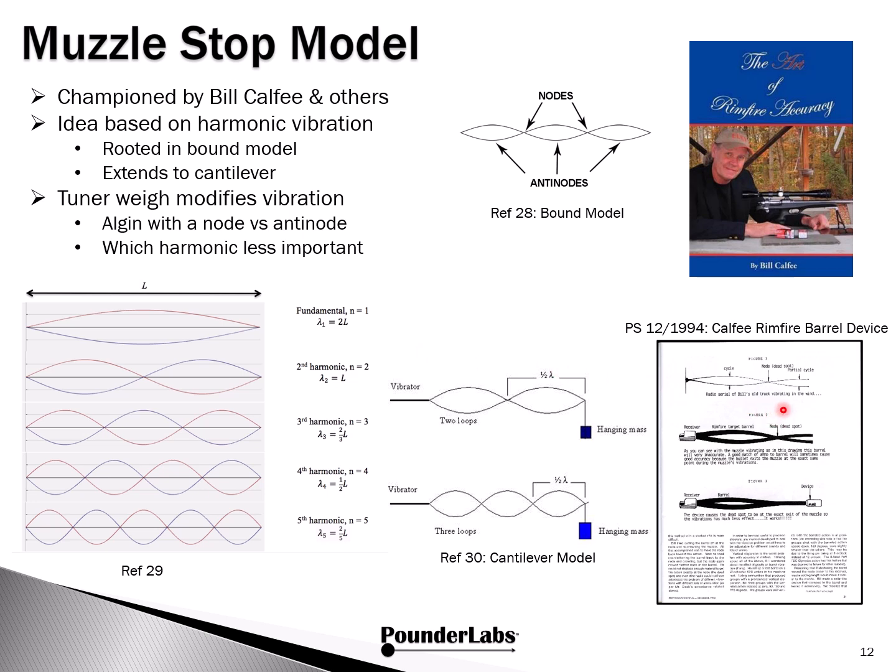Here's an article from '94 that's explaining the Calfee experiment. He observed the vibration of an aerial on his truck, and this is what he saw. You now can recognize that this vibration going on here is in between the fundamental and the second harmonic. So he's envisioning that this is how a barrel can vibrate, and you can see it's going up and down here. So the idea is to add weight, if you will, make this a virtual node to clamp out that